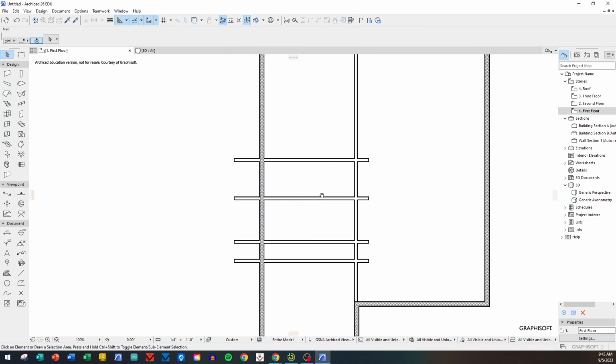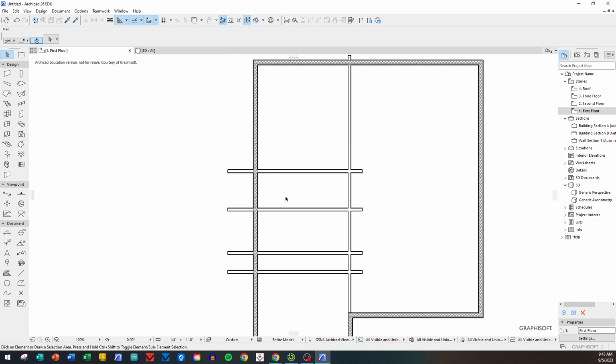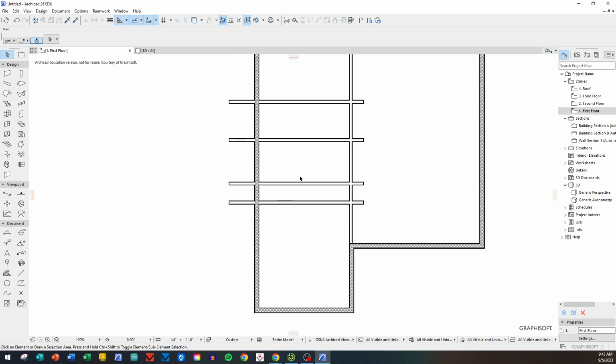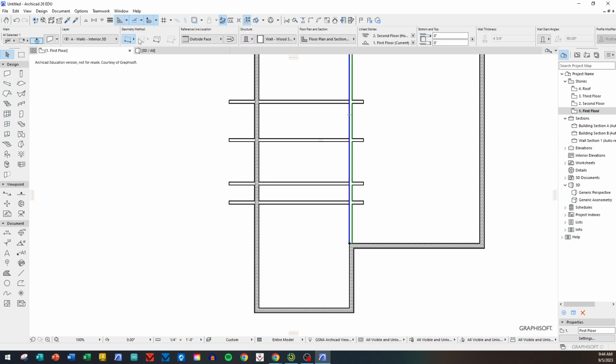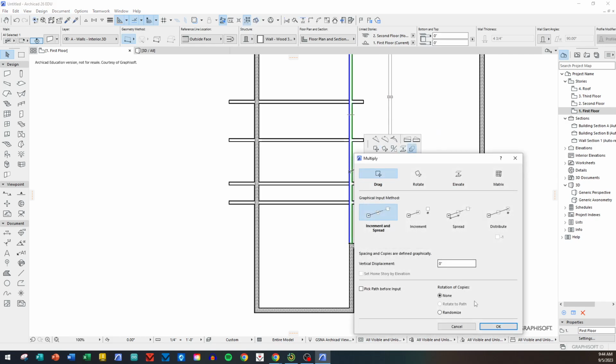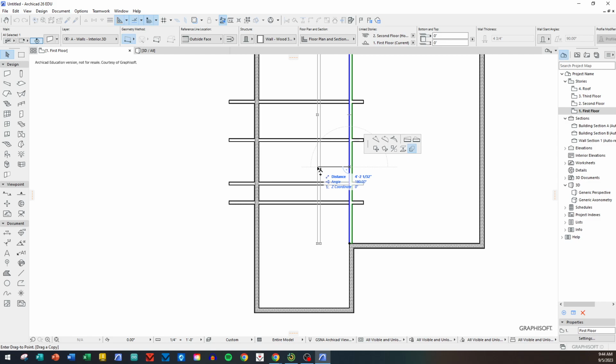Okay, so I've got the bedroom area back here, the closet here, bedroom here, closet there, bathroom in between. I need the hallway right here, which is relatively simple. It is again a multiply tool, and I go multiply. Okay, from here over this way, and that is 3.08333333 repeating. So 3.083 repeating is the same as 3 foot 1 inch. Okay, it's just the decimal foot version. Now once I get him there, I can flip him again.